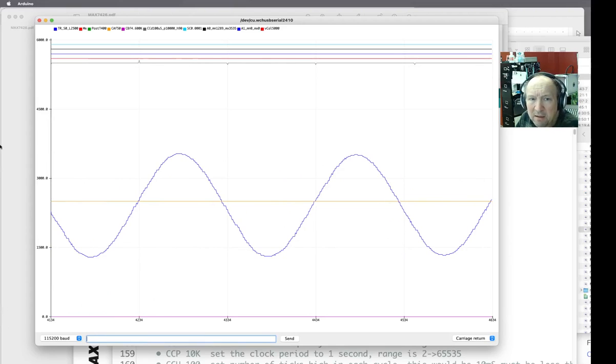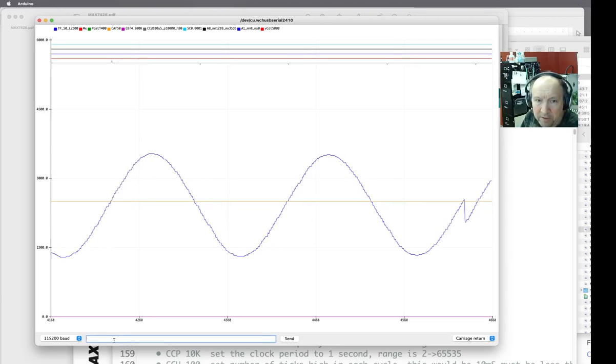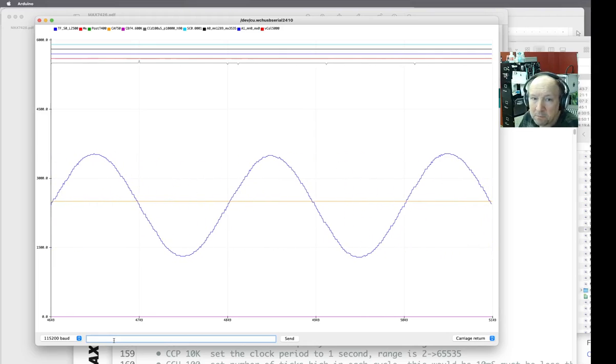And you can see in our program, here's my trigger point right here. And that coincides with the voltage going up, as I said, rising at that particular voltage. If I wanted trigger falling at that same point, I could say TF, trigger falling, and then hit another return so it triggers again, and here it is for this. Now I can feed this sinusoid into some other electronics, and then feed that back into A1, and then you can see the difference between whatever your signal did.